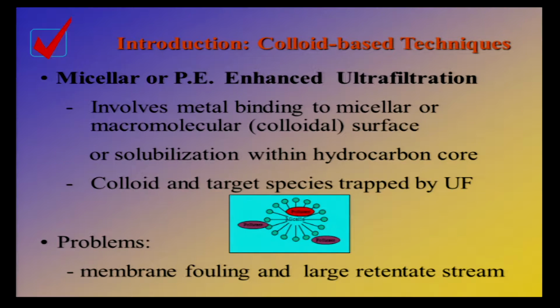Any organic molecule will be very soluble in the micelle, which is why these things are useful for cleaning. But on the outside, because we have these charged groups, anything that has a charge, in this case the heavy metals, will be adsorbed onto it. So the idea is that we form the micelle, and then we adsorb the heavy metals from the solution. And this structure is quite large, so the distance across here could be 5 or 10 nanometers, and it's large enough to be trapped by ultrafiltration.